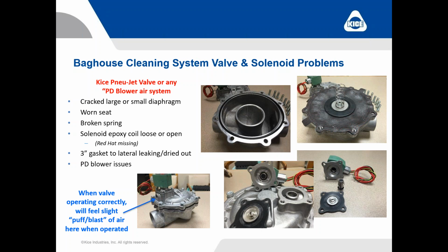So the easy way to find out why you're not holding pressure in your air tank is to look at your blast valves. Now that's, I know, a lot of times easier said than done. If you have 3 or 4 blast valves, it's usually a fairly quick job to find out which one it is. If you have a larger filter with a dozen or more, 15, 18, 20 blast valves, that becomes a little bit bigger of an issue.